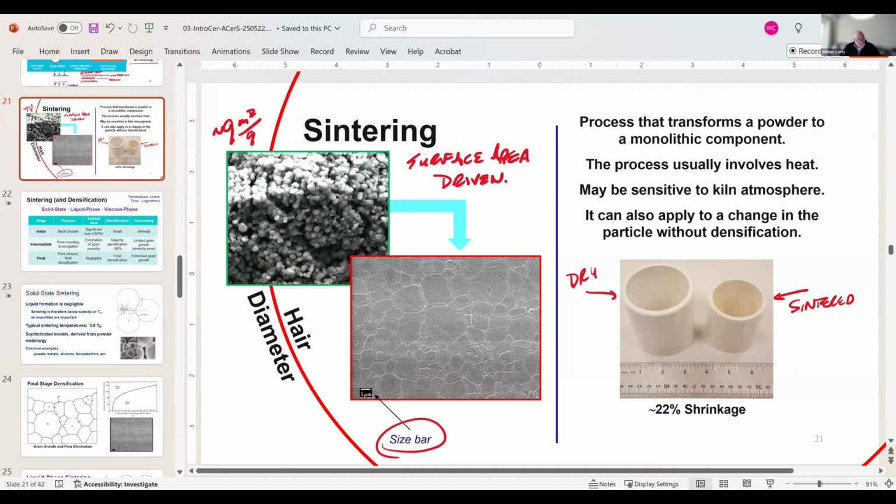Okay, and it's common to say, oh, the magnification is 1000x. That piece of information is actually useless. And the reason is that if I take an image that's this big at 1000x, and then I show the image this big, well, now it just became 4000x or something like that. And so if I put a size bar in both of these, that size bar is always correct.